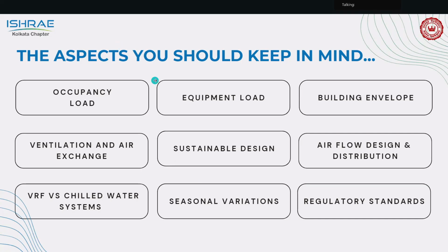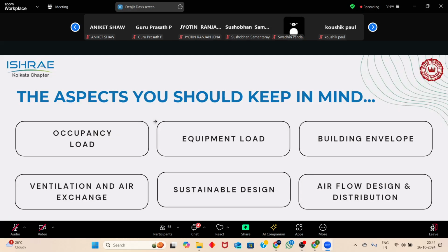True. Eighth point is the seasonal variation. For example, in Kolkata, in peak summers, you're having a certain kind of heat loads. So you need to maintain the cooling according to that. Similarly in winter, you're having a large difference there. But for example, in Bangalore, you don't feel that kind of fluctuation. So for every location or every site on which you are designing the hospital, the seasonal variations would also take place. So it's not like you can make a generic hospital design.